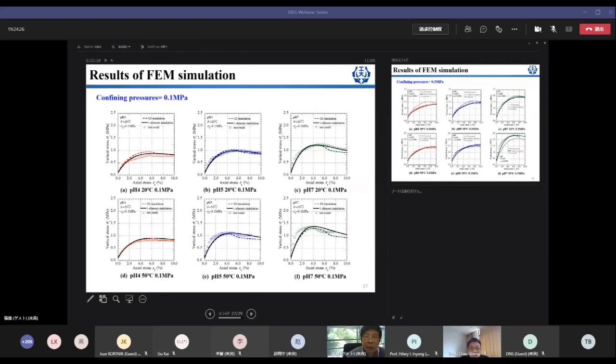Yeah. And you can see it does sometimes have an effect. In some cases, you can see the dashed red line represents the 3D simulations. Okay, this is the vertical stress and vertical strain relations. It's obtained by averaging all the elements. You can see it looks similar, but sometimes has 0% to 10% of errors, and sometimes it is different.